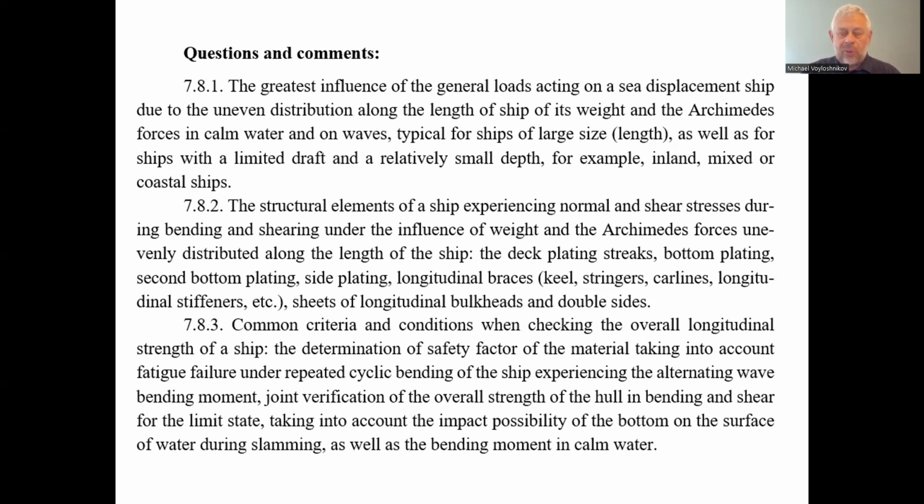But in this case, if we don't use the ballast, we will have the opportunity of slamming, the impact of the water on the bottom, due to the inappropriate trim of the ship. In this case, we have to increase the factor of safety to exclude the fatigue failure of the ship.